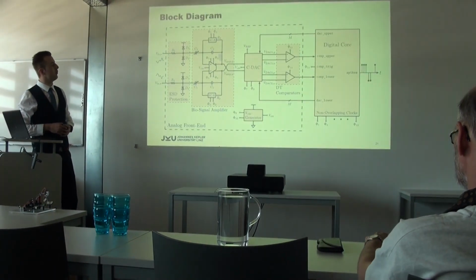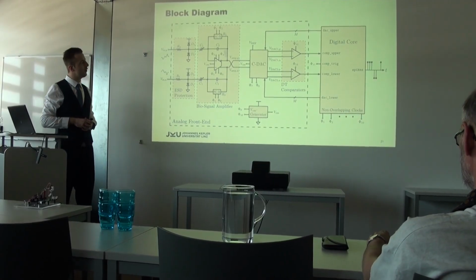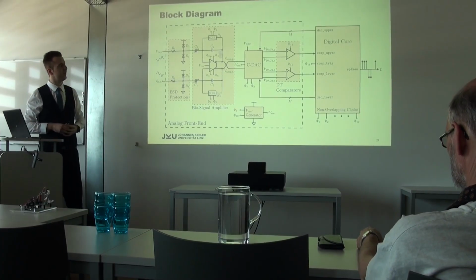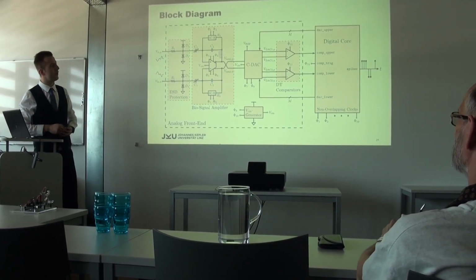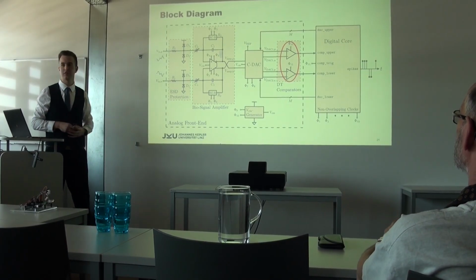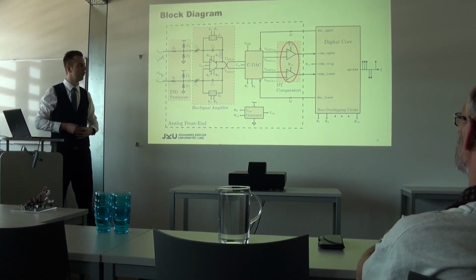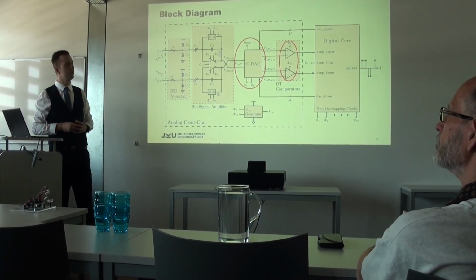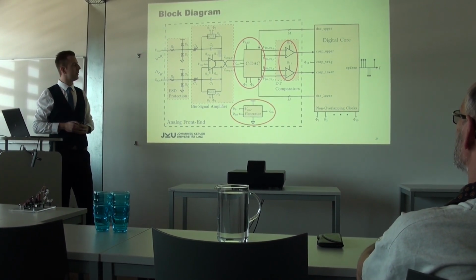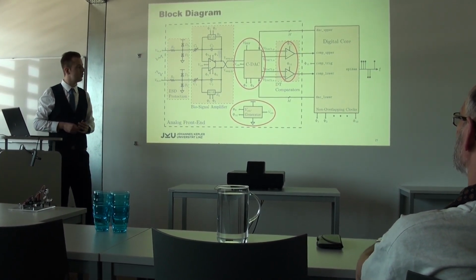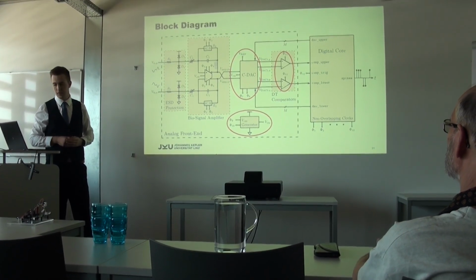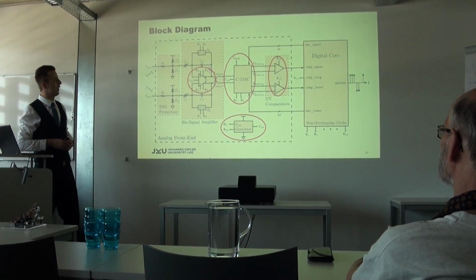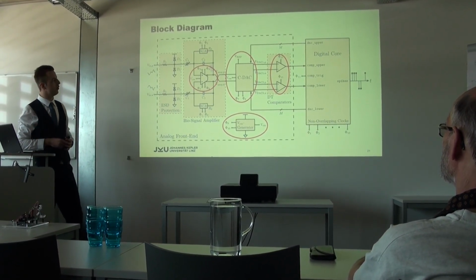And finally, we come to the ASIC design. Now we see the fully differential fixed window discrete time event-based ADC with adaptive thresholds. For that, we need discrete time comparators, in this case dynamically biased ones, so we further reduce the power consumption. I implemented a capacitive DAC with 2 fully differential outputs, and to obtain the common mode voltage, I implemented a bufferless charge pump, and the input is amplified with a biosignal amplifier, a low power, low noise one.